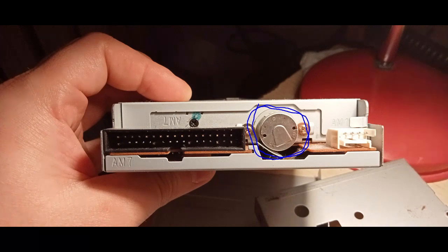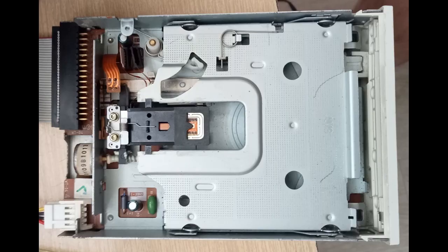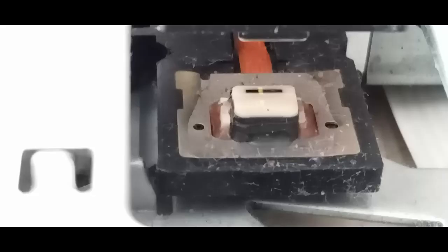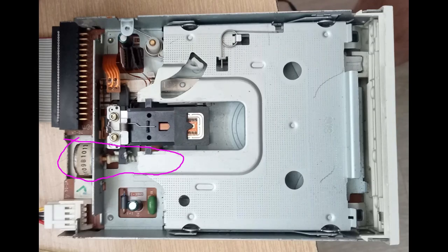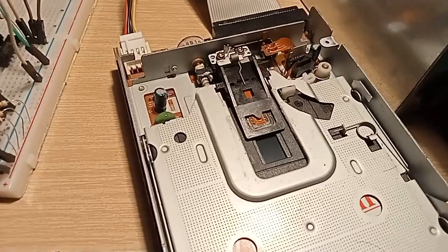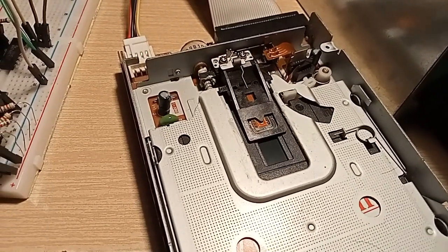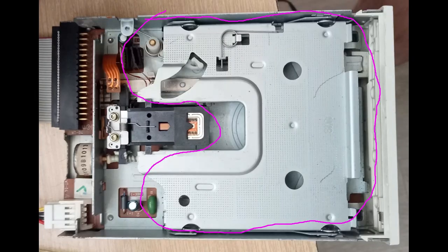There is also a stepper motor exposed. Inside the drive from the top, there is a movable head holder. It contains 2 heads, which are simply a pair of tiny coils to read and write the signal. A stepper motor with a long screw attached to the heads holder allows moving the heads in tiny steps to switch heads from track to track. Lastly, there is a mechanism that supports inserting and ejecting the disk.